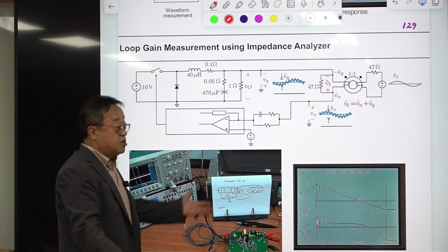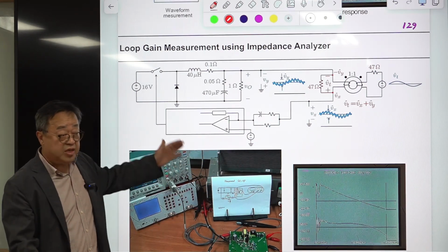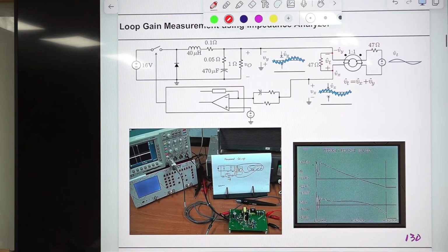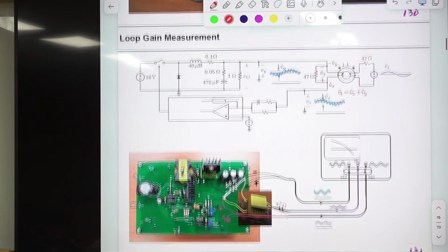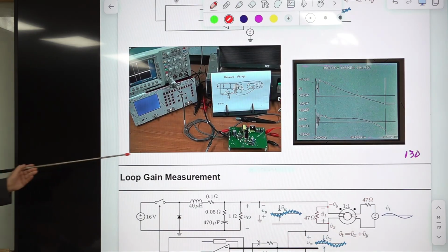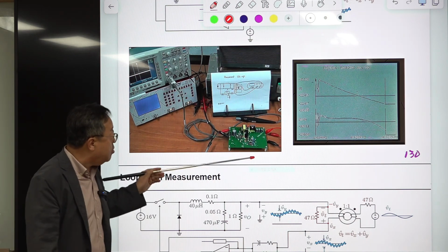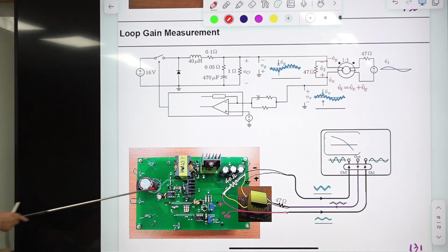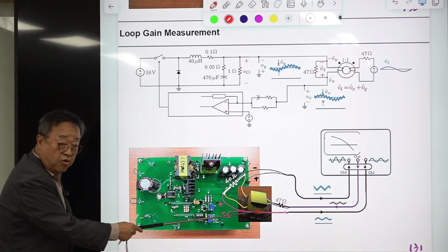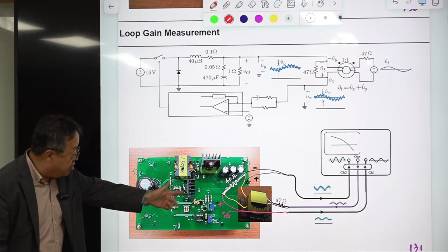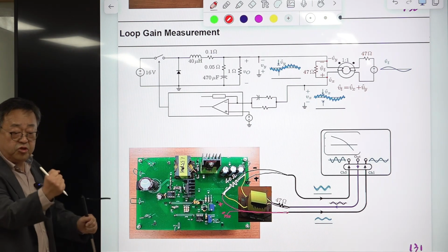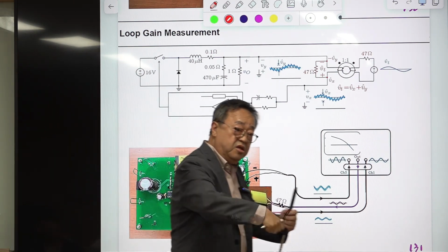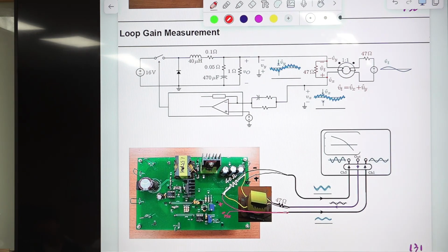This slide can move very fast. I can go fast. This is just illustration, pictorial things. Just take a look at this. And this is the setup. This was a flyback converter. I magnified it. This is the impedance analyzer, and this is a transformer. I explained, it's built on this PQ 5050 core, which is this size. There is one very diligent guy, and he wrapped it maybe 1,000 times, and we obtained this.